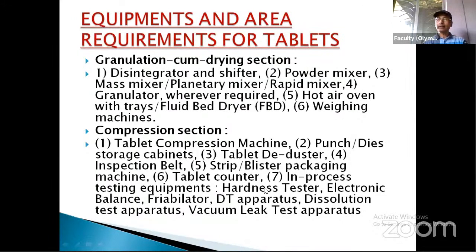You have to see the hardness of the tablet. That is very important. And if the hardness is not within the limit, you have to adjust the tablet compression machine accordingly, such that the punches can give that amount of pressure such that that type of hardness is available. So you have to always check it, especially whenever you have just adjusted the machine and started manufacturing. You will check it frequently, one minute, 2 minutes, whether it is okay or not. When you see that the required amount of hardness is coming out, then it is okay, we'll operate. And after 30 minutes or 10 minutes, 20 minutes, as per your SOP, we'll check the hardness.